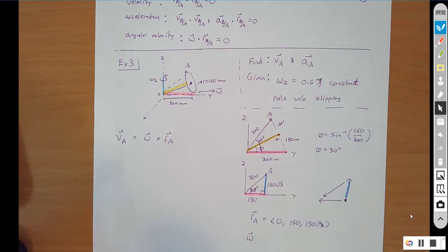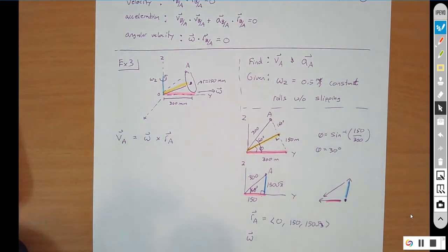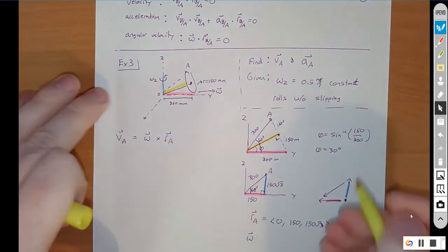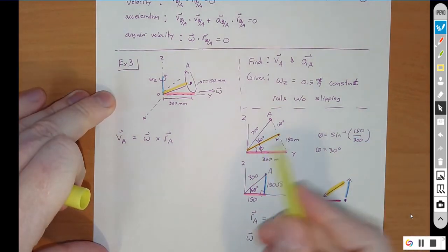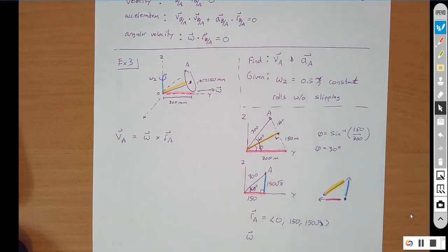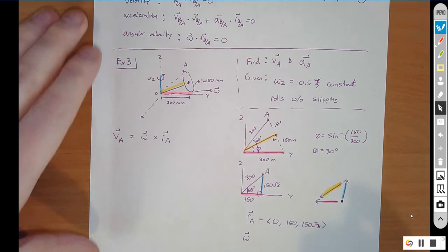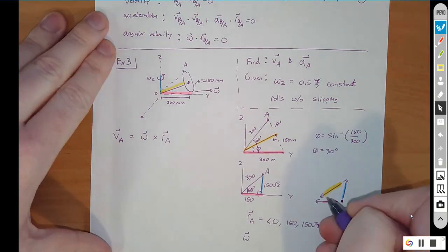This is our axis of rotation, and this hypotenuse line here is just this bar in the middle, so I don't actually have to find that. If you want to do vector math, you can find it. You'll end up with simultaneous equations for omega z, which I would call omega spin, and then you have omega down here. You could do that, and that's what the book does. But I'm just going to use this 60 degrees to relate them.